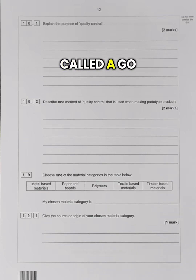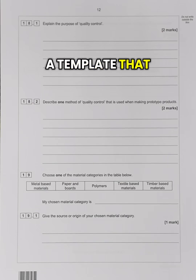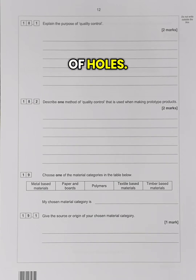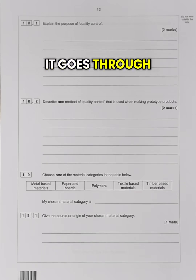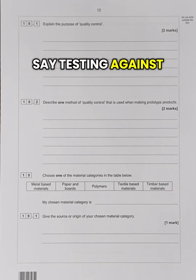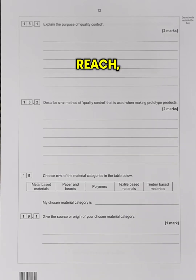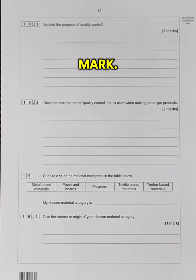There is something called a go, no-go jig, which is basically a template that has 2 types of holes. You put it through one, if it goes through that one. If it doesn't go through the second one, it's a no-go. You can also say testing against the specification, which is the standard that you are trying to reach. So that will also get you a mark.